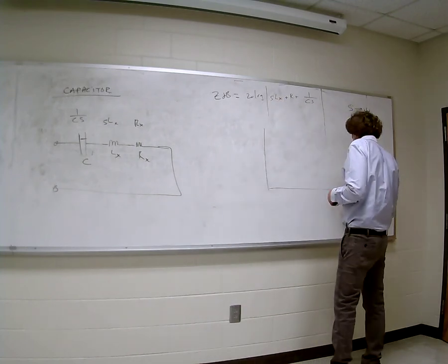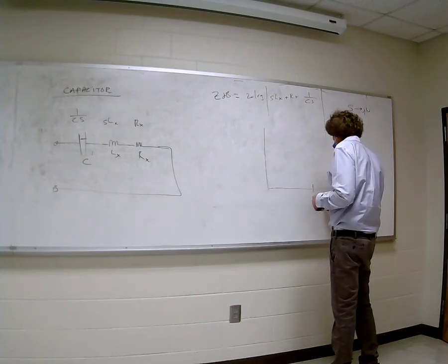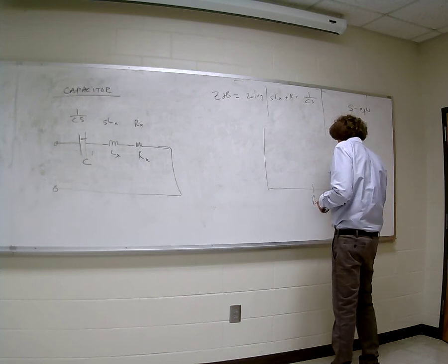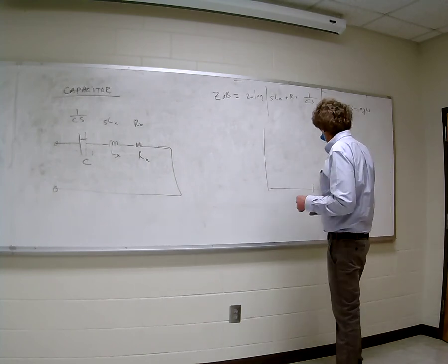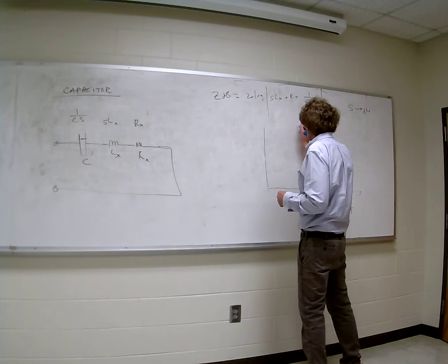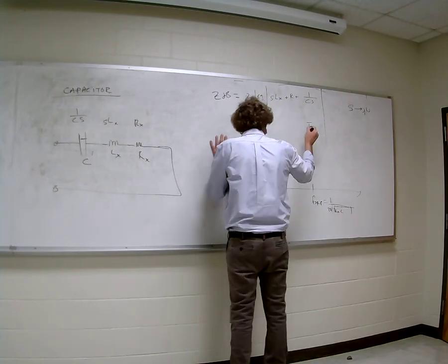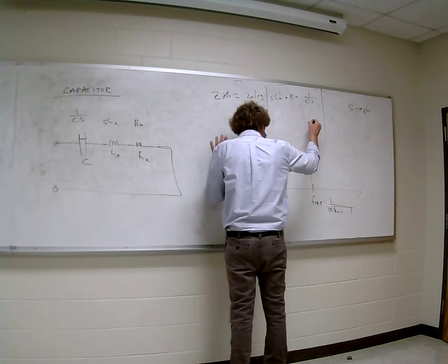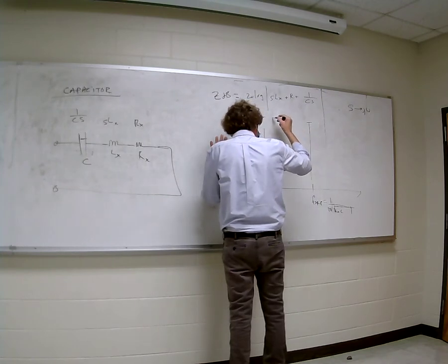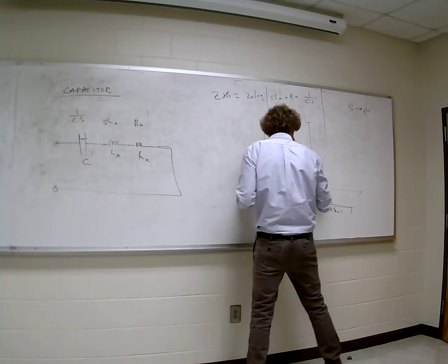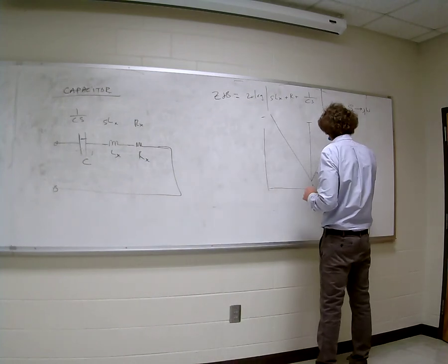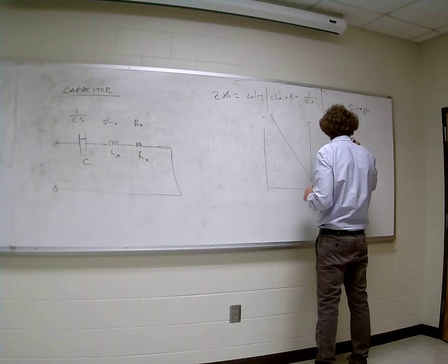If we take a look at this and put F, the self-resonant frequency, here, that will be, as the others, 1 over 2 pi square root of Lx times C. This is going to be the value at self-resonance, it will be 20 times the log of that right here. For a capacitor, it's going to come from infinity, hit this point, and then go up, and this will be plus 20 dB per decade here.